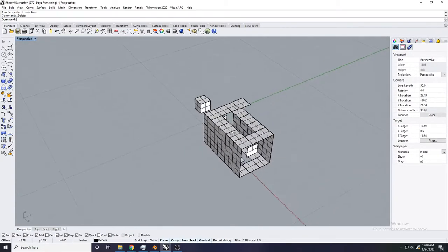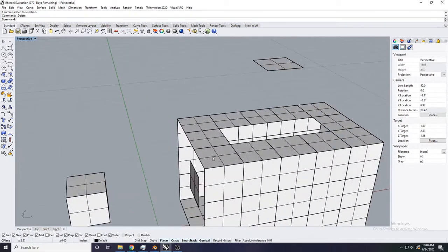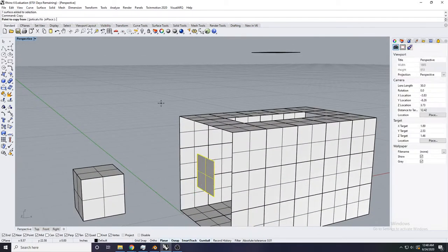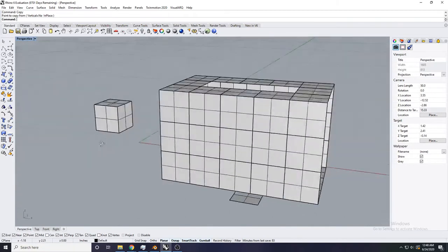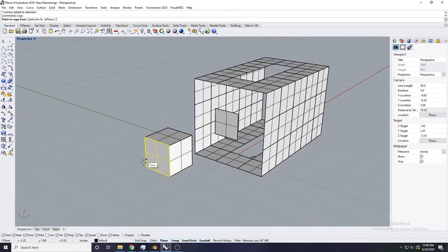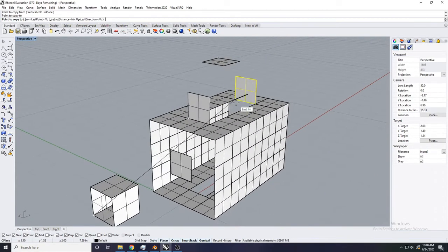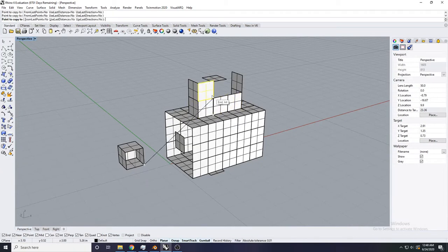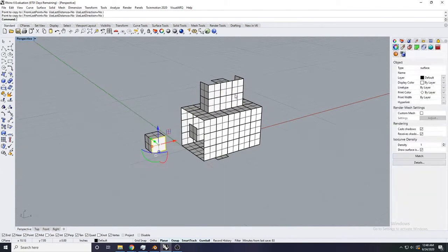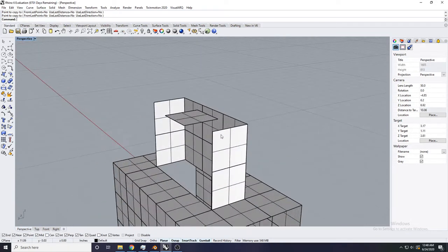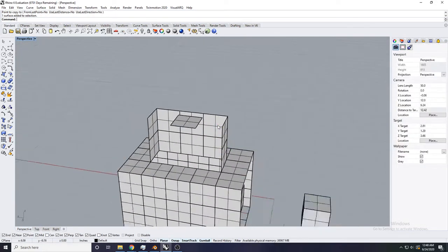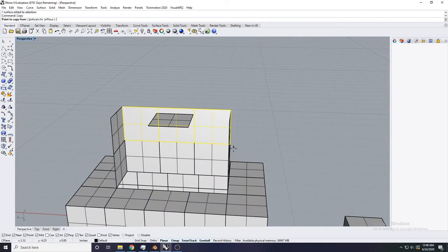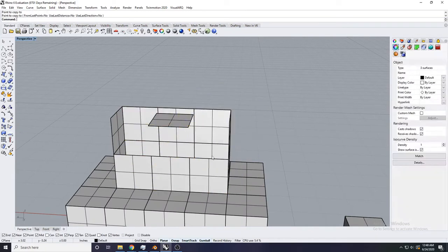And now we are going to take the side ones. You can also use this box as a view cube, so you can say, I want a side piece, and then just copy here. Something like this, I think, could be appropriate. And then, okay, I want these side pieces. So you're basically making a topology for the mesh that you will later on use. So I'm going to copy this. It's a lot of basically just copying here.